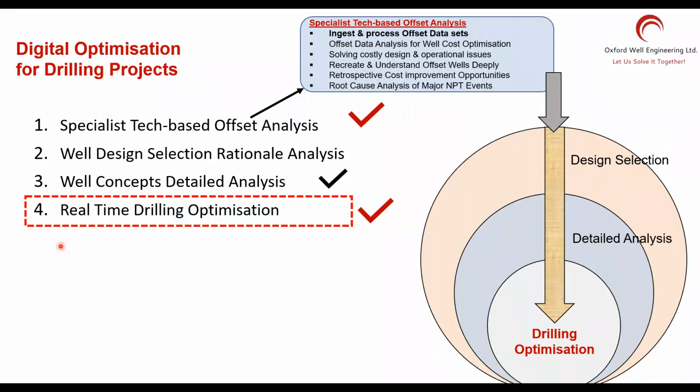If you have done a good job with offset analysis, every failure, any failure, you get to see it happening. You will see them happening because you recreated the well, the events that are leading to the failures, stuck pipe, for example, having problems getting this and getting that. You will be able to see the true root causes supported by the data.